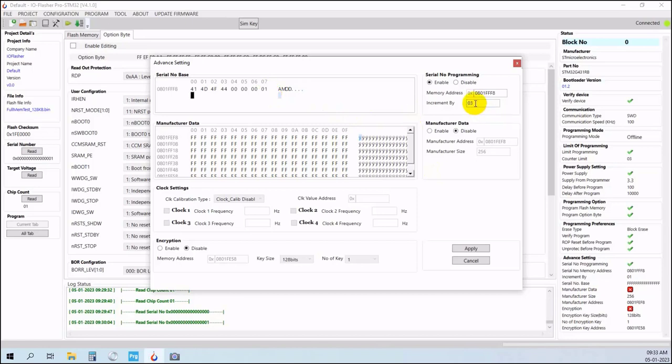In programmer 3 again you increment by 3, but you change the serial number to 2. So programmer 1 will start from 0 and increment by 3, programmer 2 will start from 1 and increment by 3, and programmer 3 will start from 2 and increment by 3. In this way, each device programmed from a different programmer will have a unique serial number.